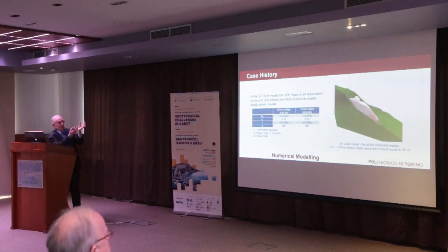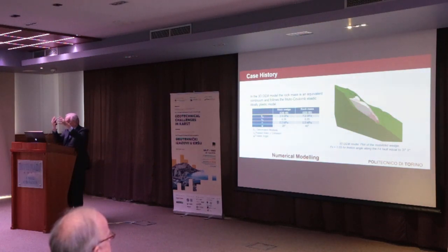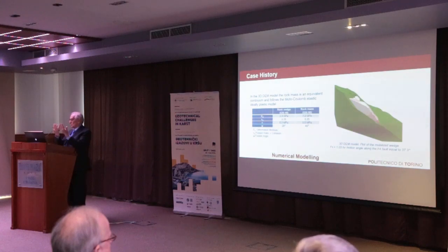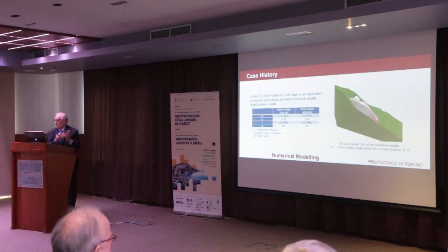You can see this picture. You can see that I am at the condition when the rock mass volume, the 340,000 cubic meter volume, is being mobilized in 3D condition. For the same angle, 37.3 degree along the F4 fault, and with the same condition as far as the waterhead, I estimate a safety factor which is a little bit higher, which is quite obvious, because when I have three-dimensional modeling, I have the three-dimensional features of the F4 fault.